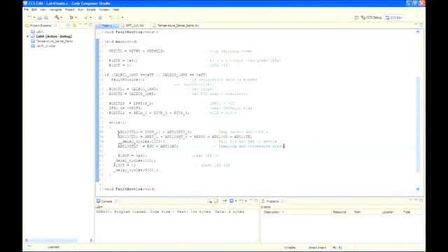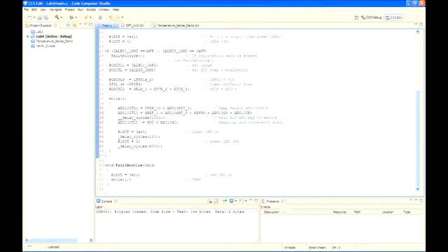So let's examine those code lines one at a time to make sure they're doing what we need them to do. You'll need to open up your user's guide and header file for reference again. It might be easier to keep the header file open in the editor for reference. So first thing, let's change that ADC10 div under 3 to ADC10 div under 0. The ADC10 control register 1 is one of the ADC10 control registers. Inch under 10, that's input channel 10, selects the internal temperature sensor input channel. ADC10 div under 0 selects divide by 1 as the ADC10 clock.